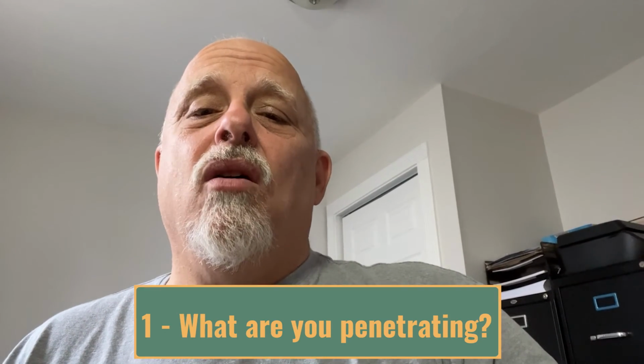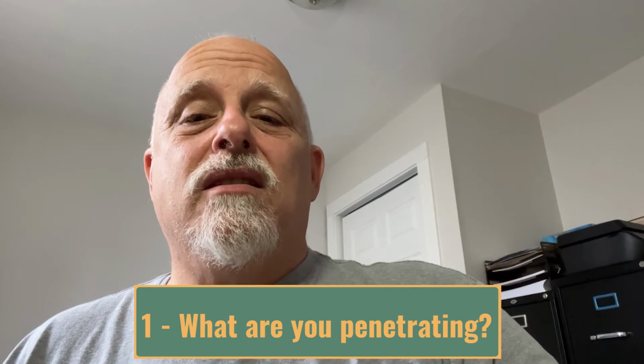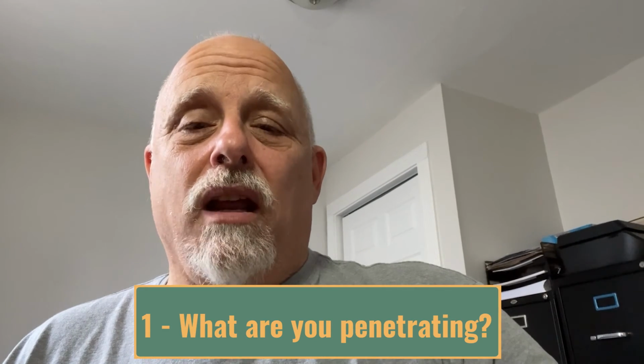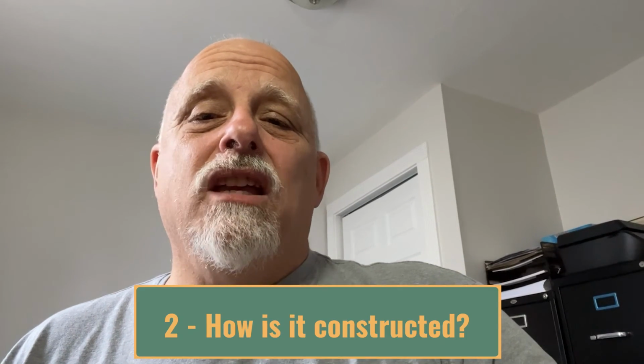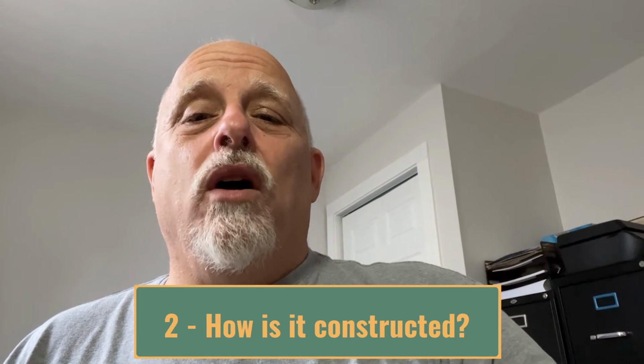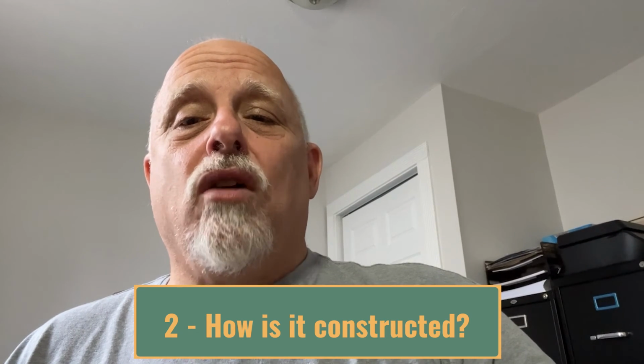First, you're going to need to know what is the system that you're going to be penetrating. Is it a floor or is it a wall? These systems are different in how they are made, they're different in how they are tested, and they're different in how they are installed. That's why that's important. The second thing you need to know is what was that floor or wall constructed of?